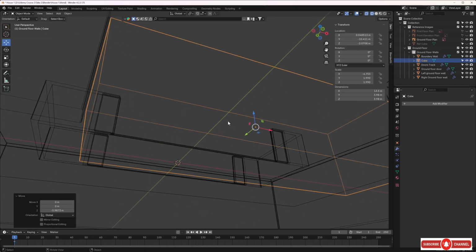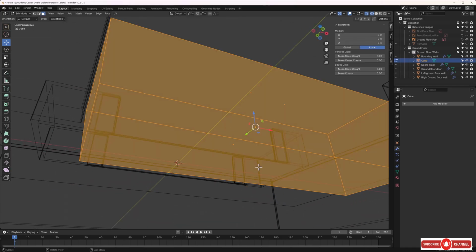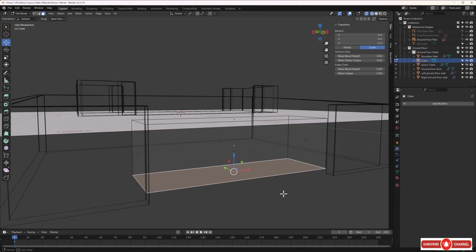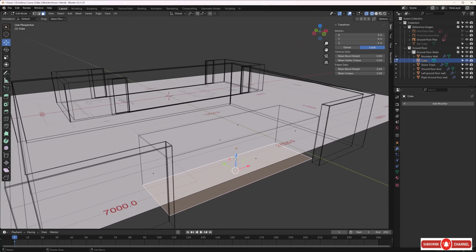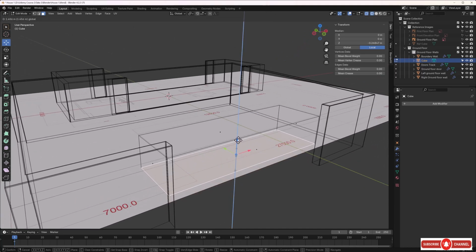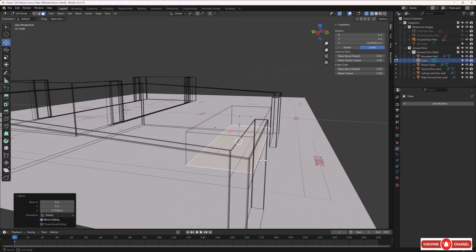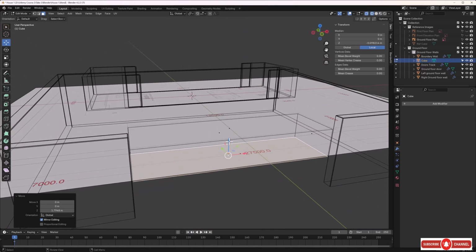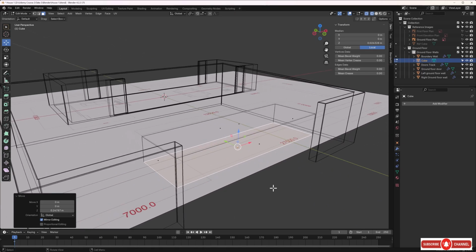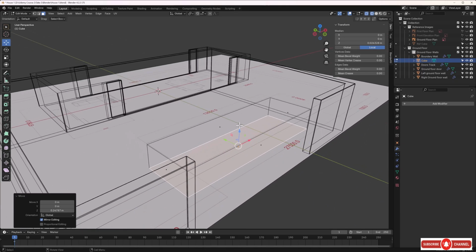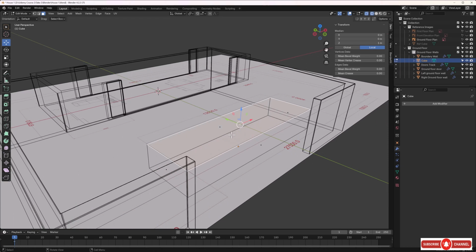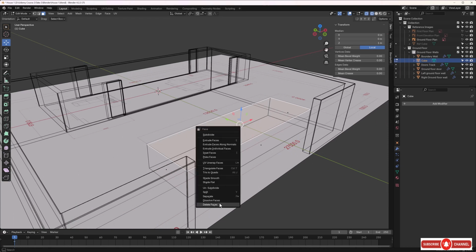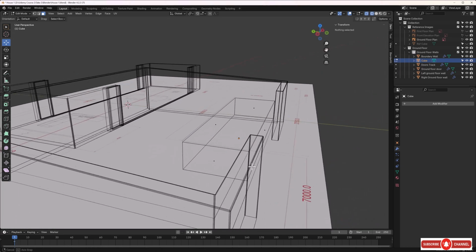And let's have a look at the depth. Let's tap into edit mode, grab this bottom face here, and maybe bring this up to what looks like about the right depth for a swimming pool. Maybe something like that would be about right. Maybe a little bit less. And that looks right to me. Let's get this top face, just click on this one, and let's right click and delete that face. We don't need that anymore.